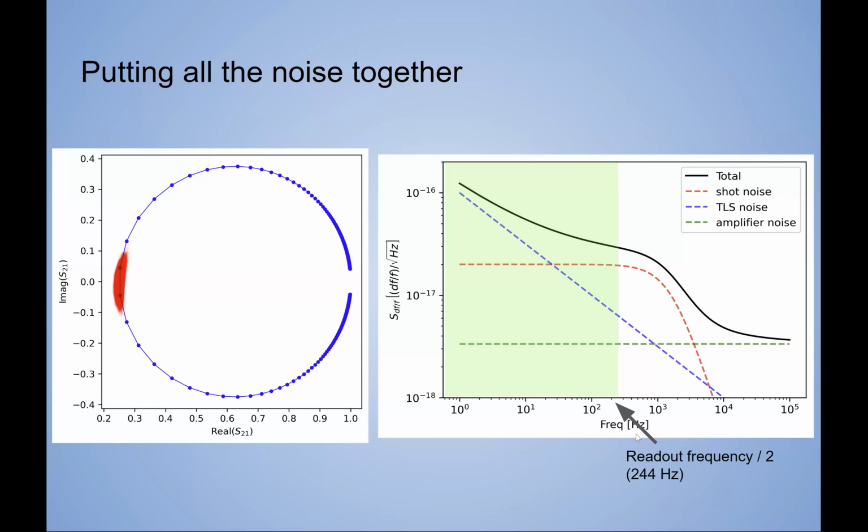And then on top of that, another strategy for avoiding this low frequency noise is what's called chopping, where you take a black piece of paper or something equivalent, and move it back and forth in front of the detector at a rate of like 10 hertz and difference it. So you just average on-off, and that'll get rid of fluctuations below the chop frequency. So anything below 10 hertz, you're essentially not seeing the noise from that. You're removing it through this process.